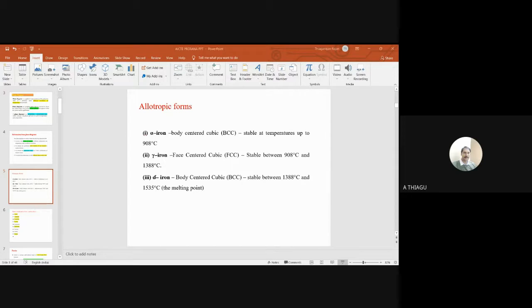It is when austenite is decomposed during the cooling process that it produces the pearlite structure. The maximum percentage of carbon is 0.8 percent. It looks like a thin lamellar layered structure of ferrite and cementite. Anyway, I will show the microstructure, and you can understand.